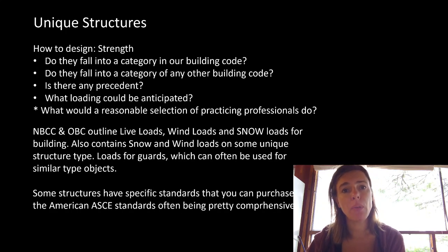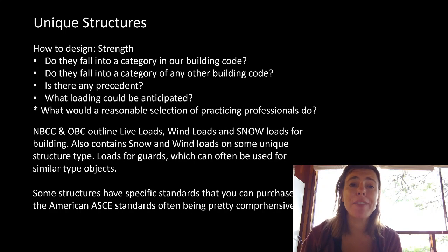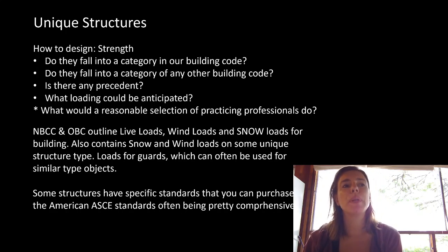The National Building Code of Canada and the Ontario Building Code outline live loads, wind loads, and snow loads. I don't know why I have snow capitalized there, but for whatever reason I felt it was important for buildings. It has some unique structures for snow and wind, but not that many. That's where we might go to a different code. Like I said, loads for guards are in there, and often we can extrapolate.